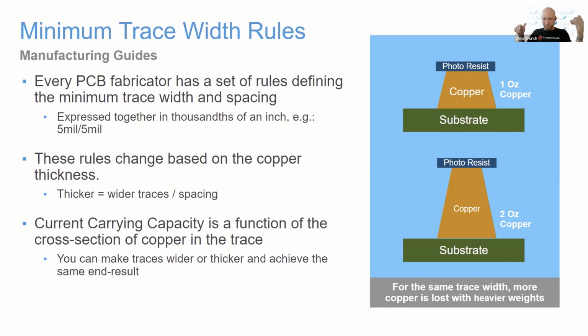But if your source and your sink are both on the same side of the board, nothing's actually going to flow through those traces on the bottom, right? Because it's going to have additional resistance by having to go all the way through those vias, down, across, and then back up. So the only way that can really work, and you can take advantage of that, is what we call balancing out the sources and the sinks based on their current load.